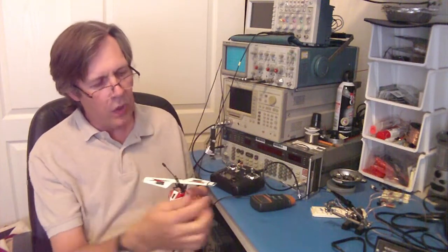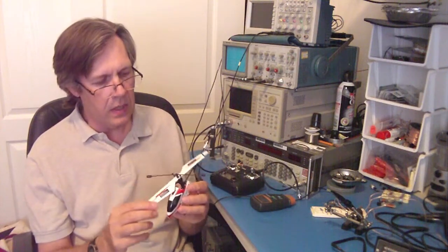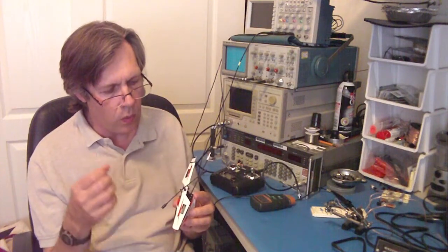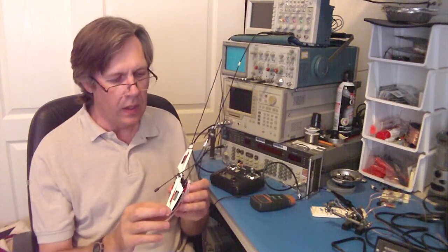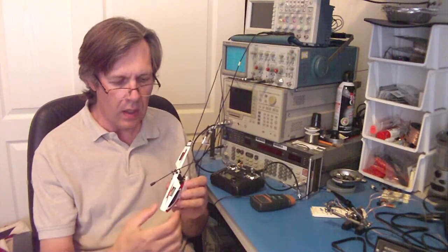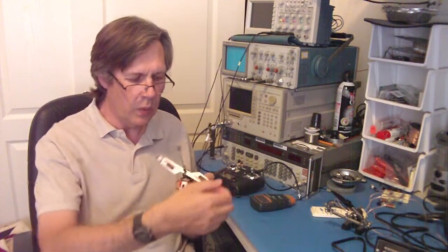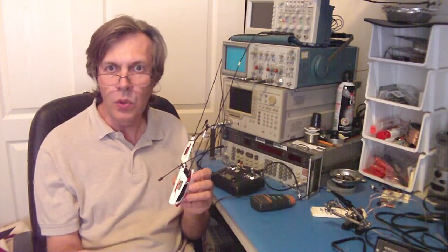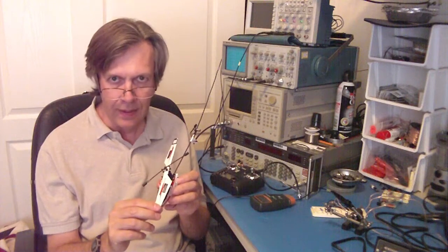So in the demonstration, we're going to watch what happens with the marked blade and the unmarked blade, because one of the things that we're going to be looking for is when something is rotating at exactly equal to the sample rate. In other words, we take a sample and we see the rotor, say, in this position. If it rotates exactly one full time and then we sample it again, it looks like it hasn't moved. And that's aliasing, because the alias is it's masquerading as not moving when actually it is moving.